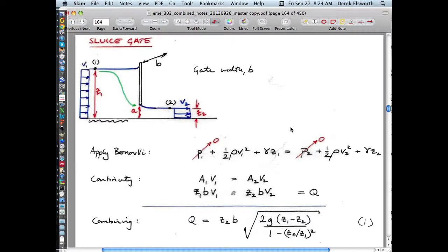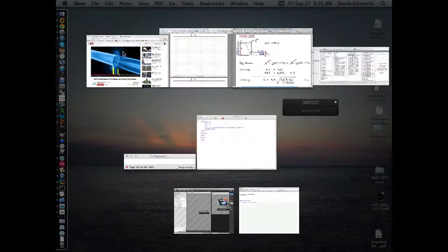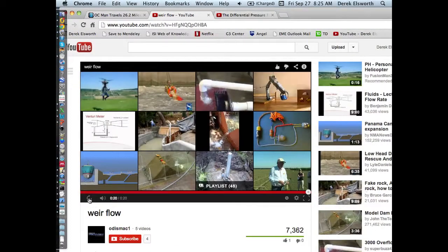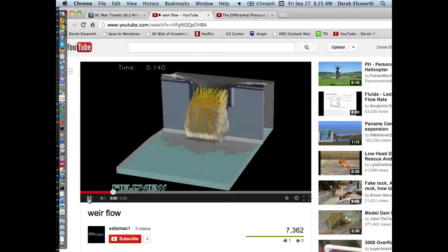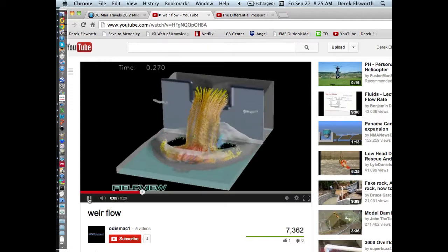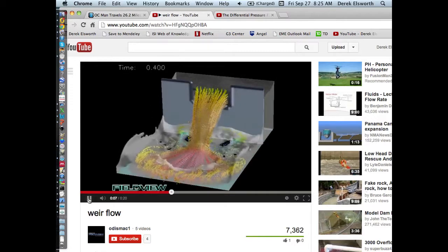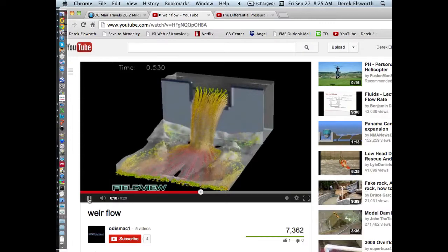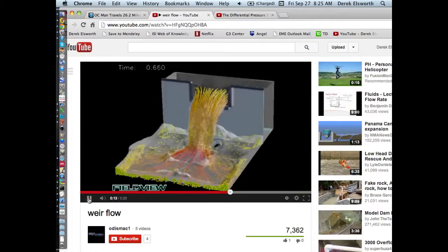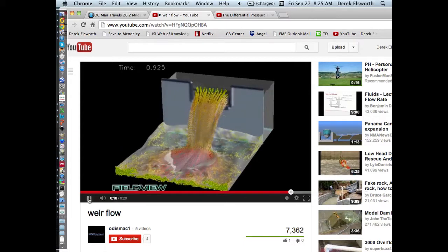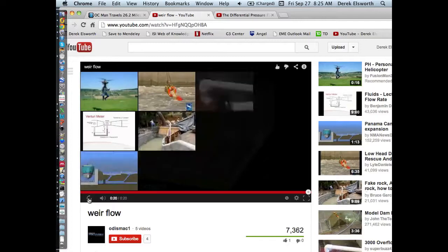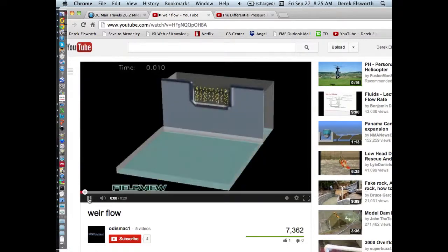So how you solve it is being able to measure fluid pressures. Flow in open channel flows is a similar idea. Again, let's look at this. If you go into the field and you want to measure the flow rate in a small stream, a typical way is you march into the field with a piece of plywood, which is 6 feet long, 2 feet high, with a box cut in it or a V-notch cut in it. You block the stream, a small stream that you have, and you just measure the height the water comes up in this either square notch or V-notch or circular notch, and you use that to calibrate the magnitude.